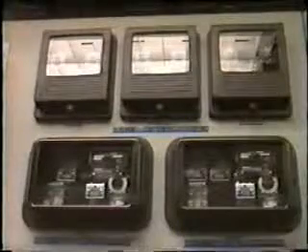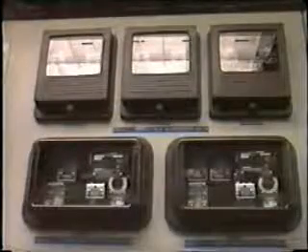Okay, based on discussion of bus protection, I think it becomes quite clear that this type of protection does present a few special problems. First, because of its strategic position in the power system, any operation of bus protection relays will clear many circuits and probably cause a major system upset. For this reason, we do not want the bus protection scheme to operate unless there really is a fault on the bus. However, when there is a fault on the bus, it is important that the protection relays operate and clear the bus as soon as possible, preferably at high speed.